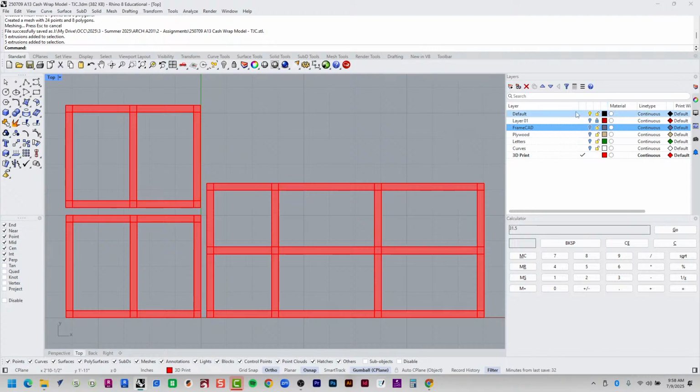If I want to be in a specific layer, you see this check mark? This one right here? You see the little check? This is in a column, right? Depending on what layer I want to be in, if I want to be in the curves layer, I need to click in that column where the check mark is. And when I do that, now that layer is bold. I'm in that layer. So now anything I draw here will be in this layer.